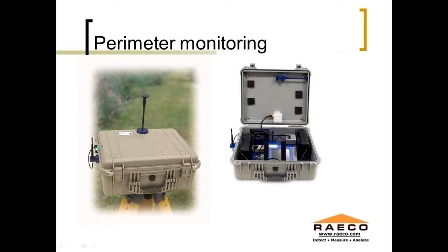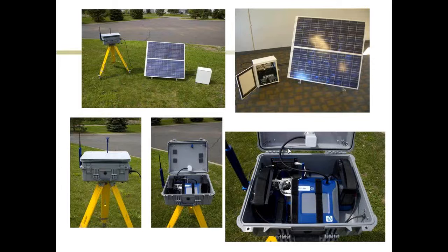And then on the left side right here we have a radio modem. What that allows is communication back to a main hub where an operator can actually see the data coming from this monitor without having to go out to the unit to see what is happening. Inside the box right here we have a little water trap, so if there is any kind of little water that gets inside this enclosure, it gets trapped in this water trap, and then we pull the sample across through this tube across to our DustTrak and we take our measurement. A lot of applications we work with. We work at landfills.